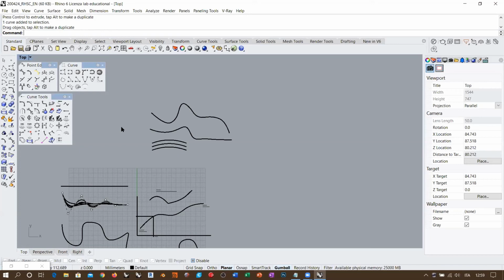So this is the general meaning, but fairing in terms of topological control means avoiding G3 discontinuities or G3 variation. So avoid the jerk phenomenon, like the curve starting to dance around and oscillate. So fairing tends to eliminate this kind of oscillation and make a curve easier to manufacture, more aerodynamic, more smooth, and so on, okay?